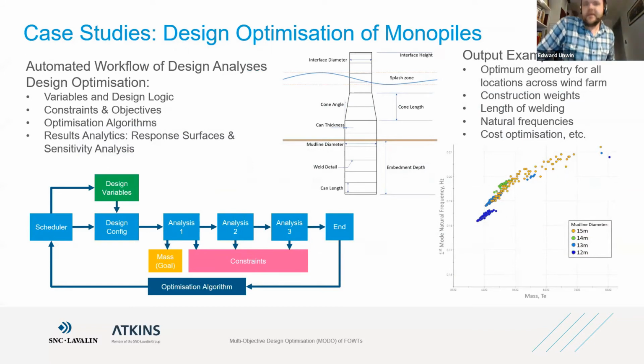So here are some slightly more palatable examples, and in a minute we end up in a floating one, which, as for naval architects, is much cooler. So here we are. For a monopile design, say there are lots of parameters that you need to vary when you design your monopile. There's how deep it goes, how long your cone is, how thick the monopile is. Obviously there are lots of things that you can't change, like the soil stiffness and the water depth, but they become fixed inputs. But there's lots of geometric things about your monopile that you can change.